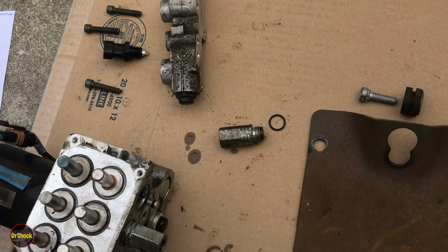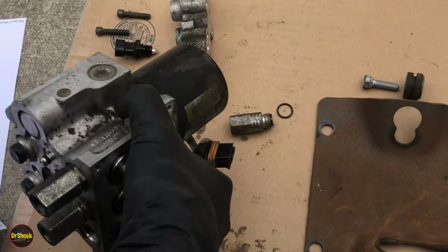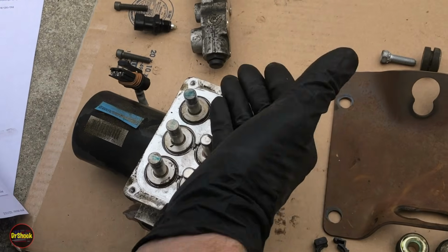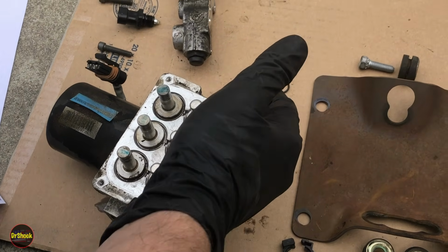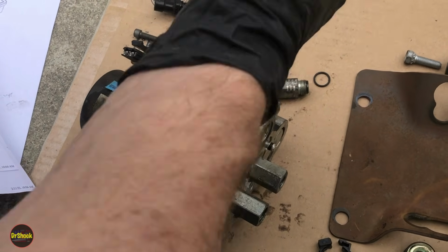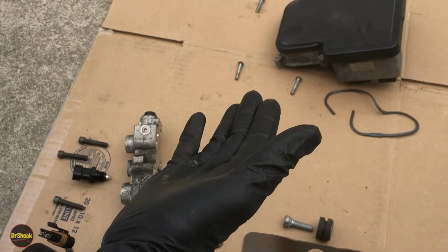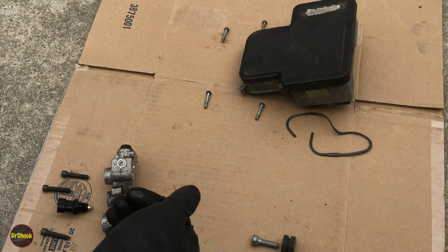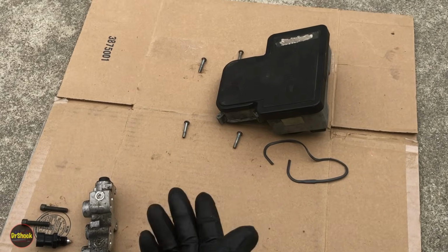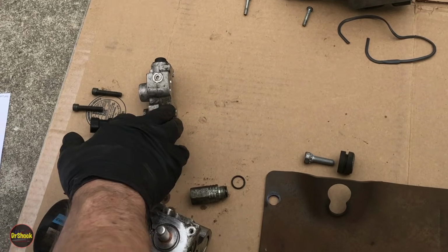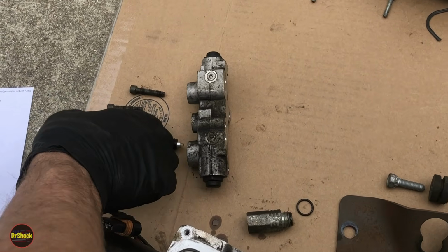Normally when you'd buy the BPMV, it would come like this. So it's exposed with these solenoids, and you would have to then acquire a new gasket. If you changed out the EBCM, it would come with the gasket, but you'd have to procure the screws, and like I said, they're torque to yield, so they get discarded after they're torqued down. If you bought the combo valve, it would come with the switch.